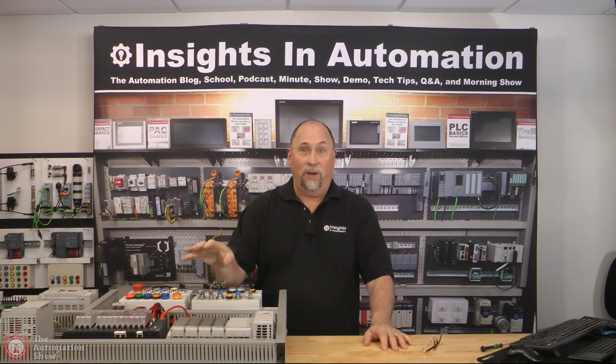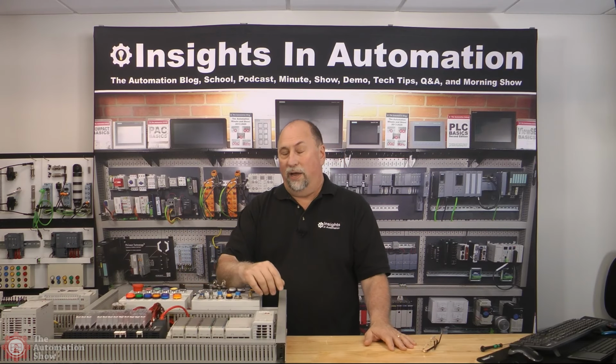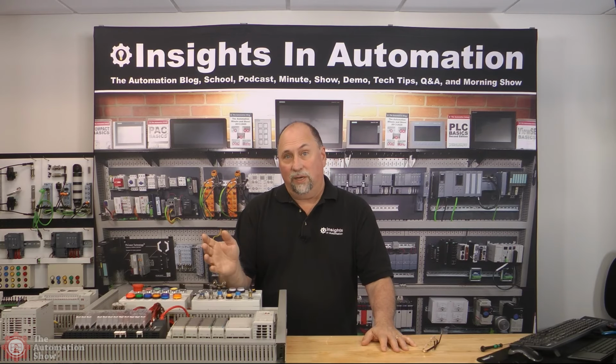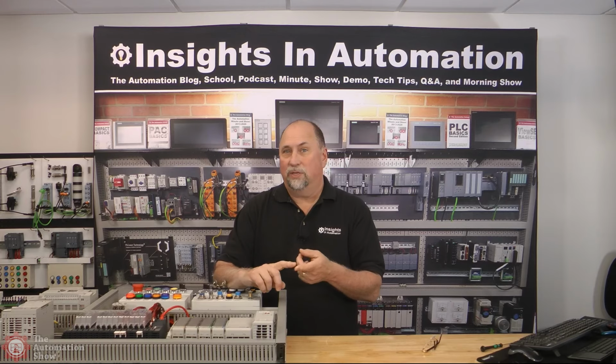Now again, I know if you're using Modicon, this is probably going to be your choice of I/O. But if you're a Modicon user who has to occasionally do maybe Rockwell, then you potentially could keep your I/O, right? Because it's multi-field bus, and use Rockwell and Modicon PLCs or PACs with the same I/O. And being that this is new and designed from scratch, with the secure TPM module inside the NIM, with secure communications on the backplane, and then security in the modules themselves, it really seems to be like a next generation I/O platform designed for security and ease of use too.